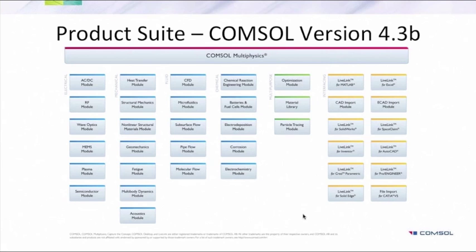If not, you can define the model with some inner variables that change with time, incorporate them into your own ODE, and then add, for example, strains via the initial strains into the COMSOL material.